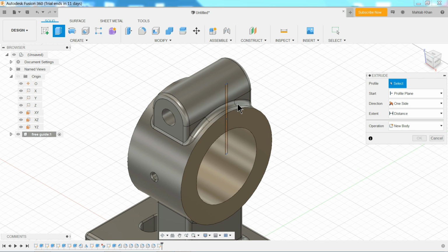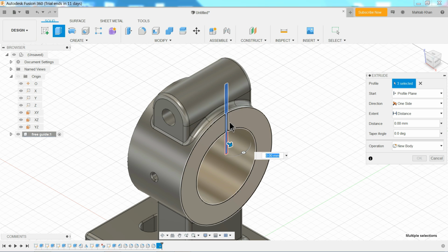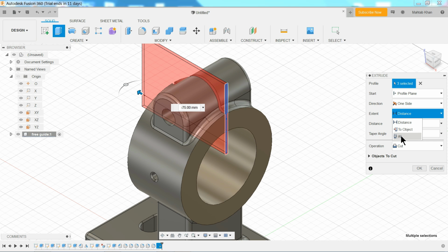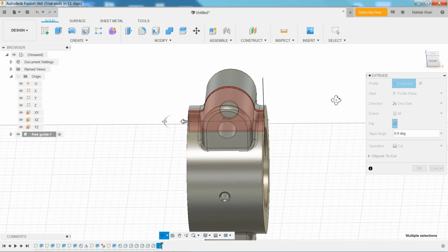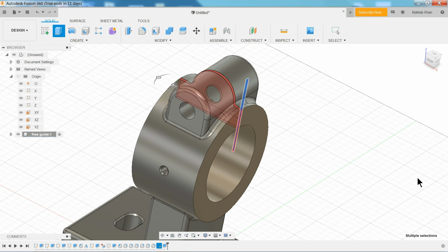Now it should be more than the length of this width, so simply finish, extruded cut. Now here we need to choose 1, 2, 3, because this is lying in one face and there are 3 closed bodies, so you have to select separately one by one. Now just drag outside here, make sure cut is selected, even though you can choose all here. Now see the shape.